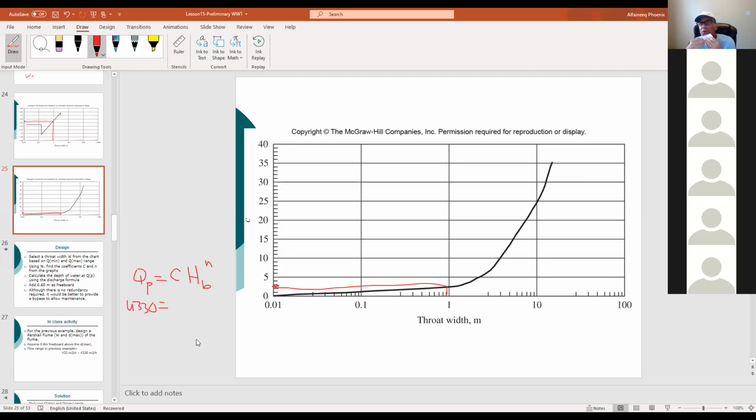You need to know the depth of water in it at the different Qs that you have: at your peak, which is going to be the highest, at Q average and Q minimum. All right. Put these numbers. You said this is 2.5 or so. H approach, or whatever you want to call it. And this is raised to how much we said this one? 1.57. And you calculate that H at the highest.